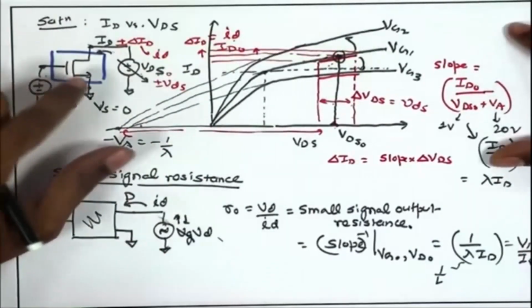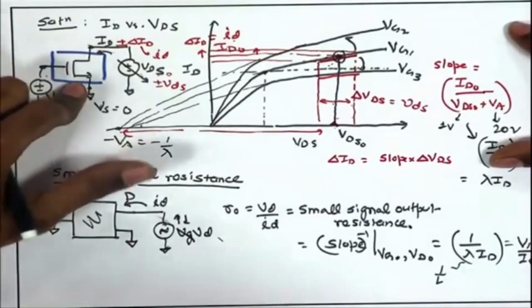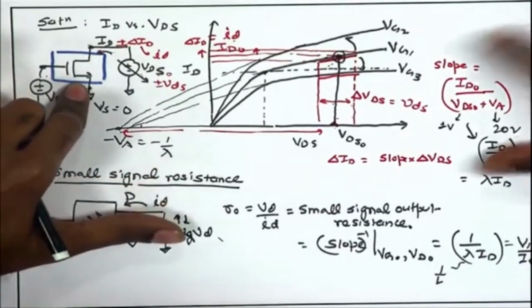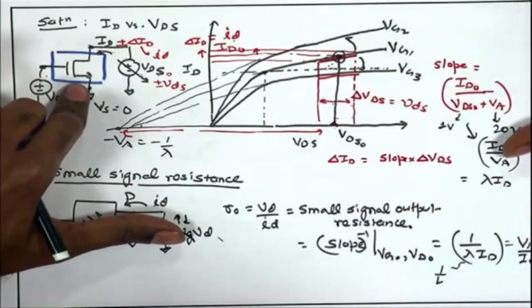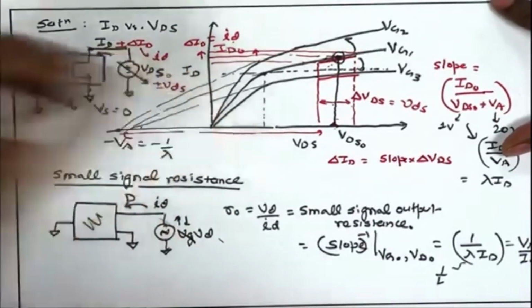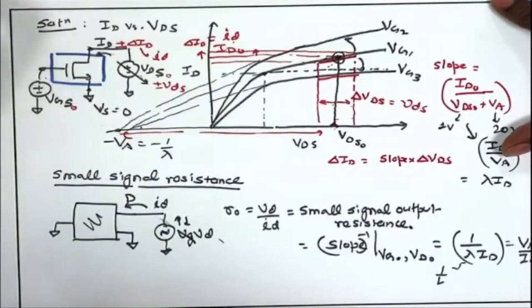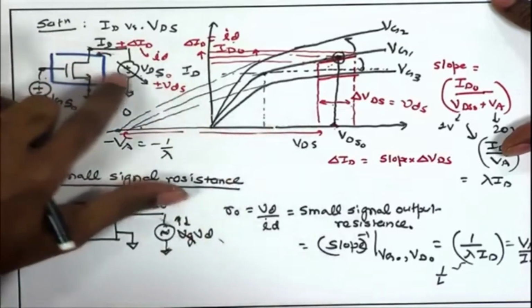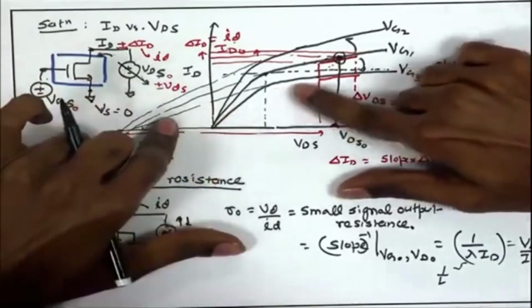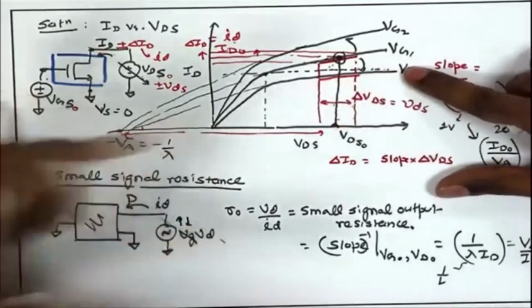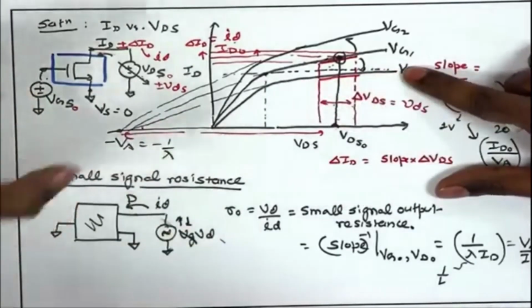use of the device. When we are going for digital use of the device, where the MOSFET is just being used as a switch, there we are not really utilizing this saturation region characteristics, channel length modulation of the device for our operation. The device is really operating as a switch and it is in triode region. So, we will see this distinction between the analog and digital operation shortly, but just to emphasize that the saturation region characteristics and the finite slope is very important for analog operation, and for having a larger output resistance, smaller slope, so that the transistor behaves more closely to an ideal transistor.